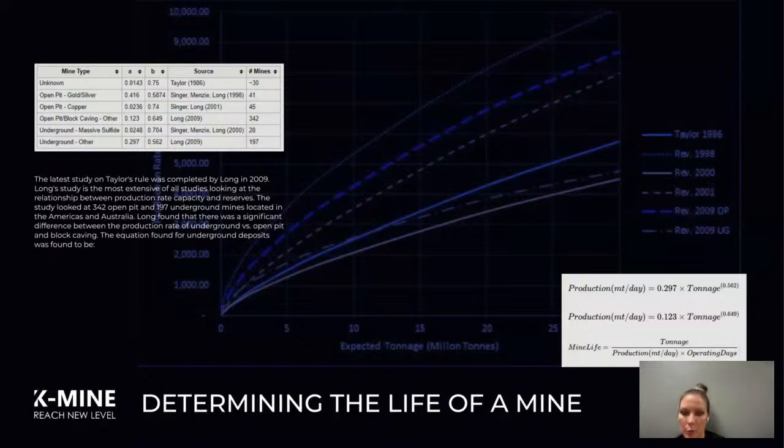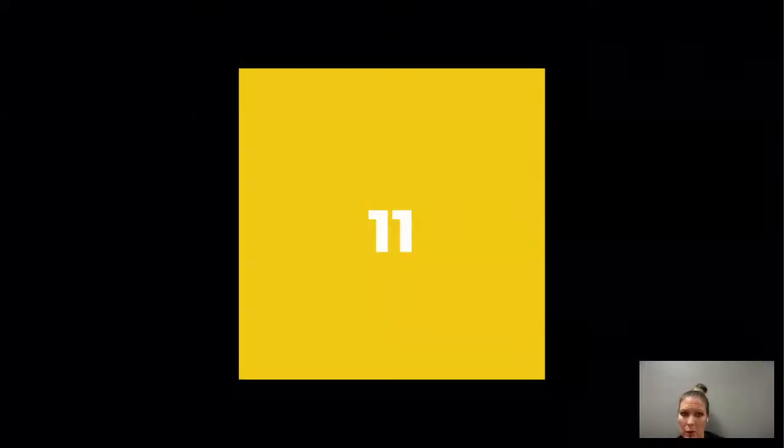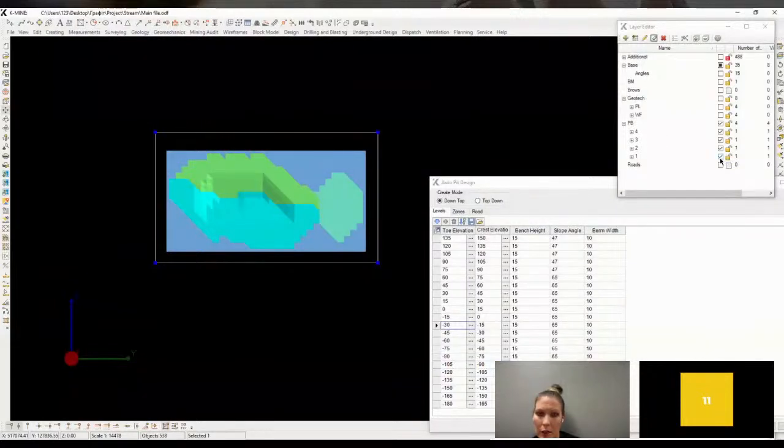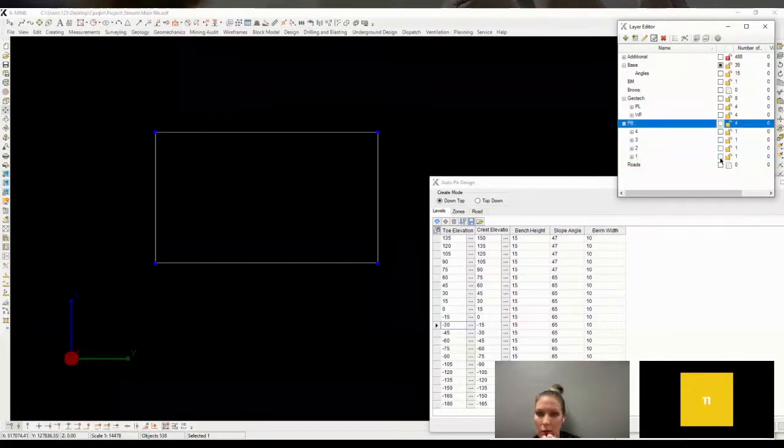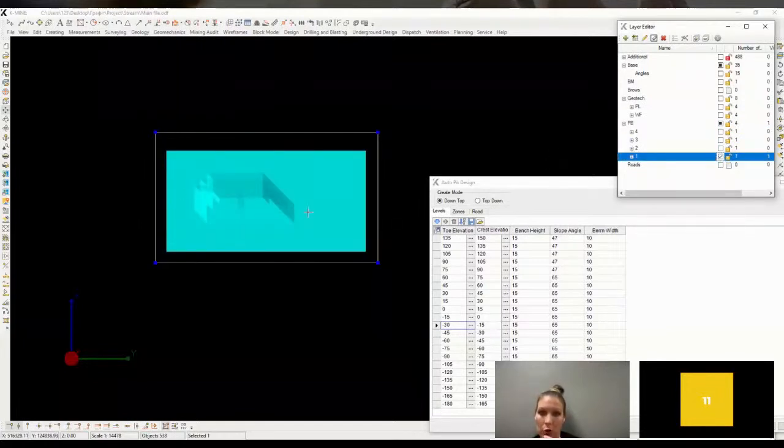First, you need to determine the daily productivity, and then using the resources of the deposit, determine its lifetime. Using the values that were obtained as a result of determining the optimal contour, this is 179 million tons, and the year-round production cycle of 365 days, we get the life of the open pit, which is about 17.5 years. So building pushback is an important step in creating a mine plan. In the process of detailed design of the final stage, the development of each pushback should be created.